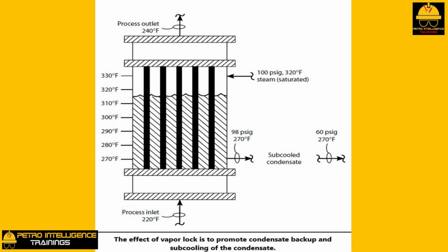Option 5, install a condensate pump and condensate drum. Pump the condensate out under level control. The drum must be immediately next to and underneath the reboiler. Also, the drum must be high enough above the new condensate pump to provide sufficient net positive suction head, NPSH, for the pump. This is, of course, the preferred, if not the typical, way of handling this very common design problem.